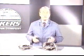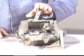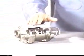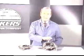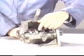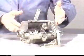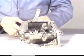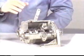Here we have 2 cutaway models of the units we've been discussing. This one is a variable displacement pump, and here we have a fixed displacement motor. The pump has a lever, which can be operated manually to move the yoke. The yoke holds the swash plate in any desired position from maximum displacement in one direction through center to maximum displacement in the other. As the shaft is rotated, we can see the pistons withdrawing from their bores.